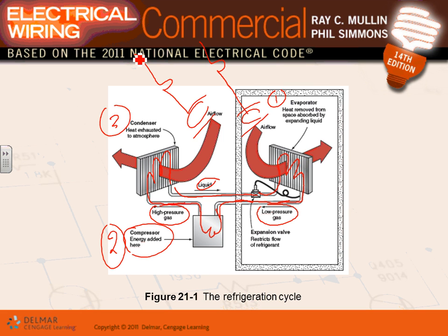And so now with that condenser, we remove the heat. The outcome here is heat. Heat is out. Remember, the heat is going here, out. Now we throw it. It changes from high pressure gas, guys, into liquid, and it circulates back again into the evaporator that continues to do the same process. That's why it's called the refrigerant cycle. It keeps going on and on.